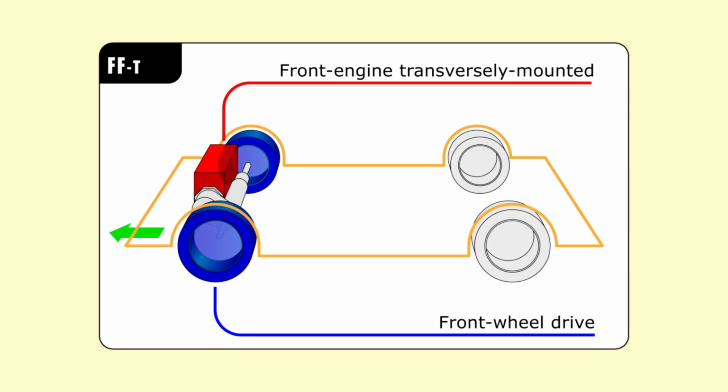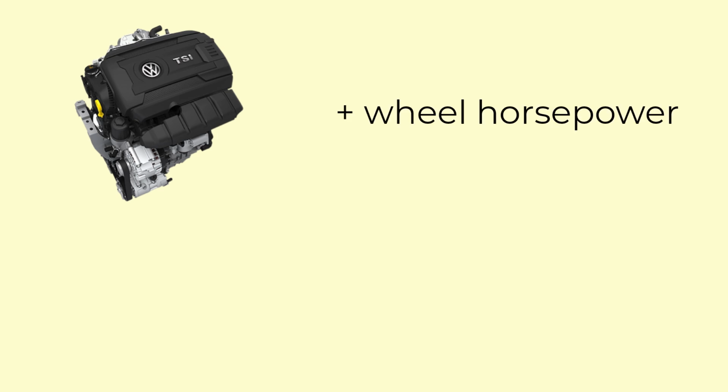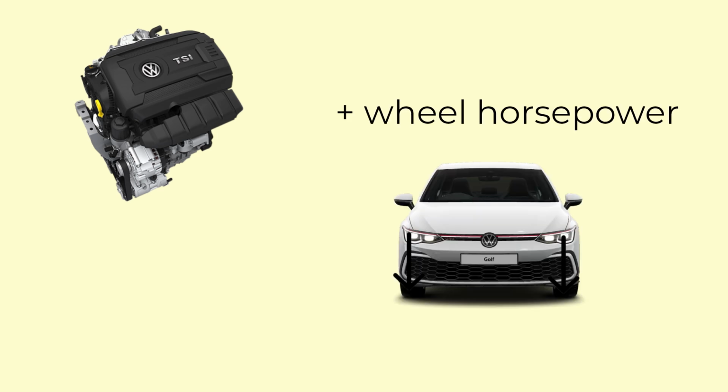From stock, front engine, front wheel drive cars tend to understeer the most out of all the layouts. But why is that? This is as the combination of the engine's weight plus the power being directed to the front wheels means a lot of weight is being pressed down on that tyre. Combined with the front wheels having to turn as well, they can struggle, leading to understeer.